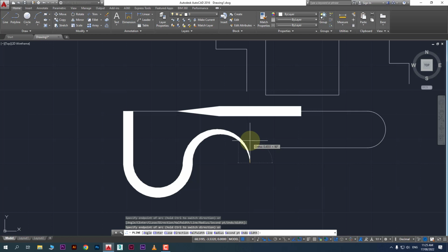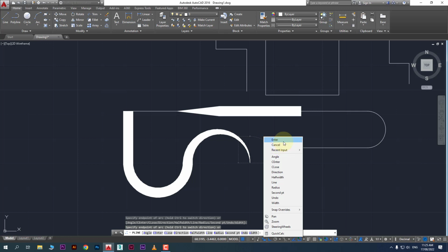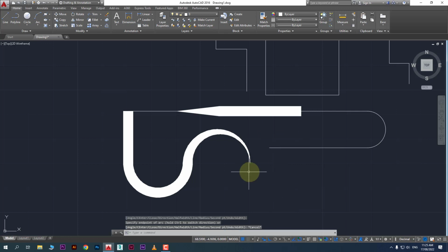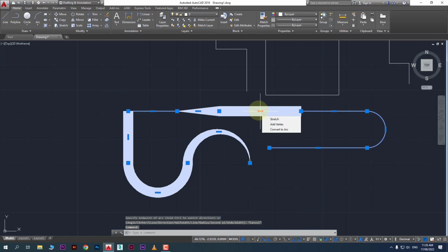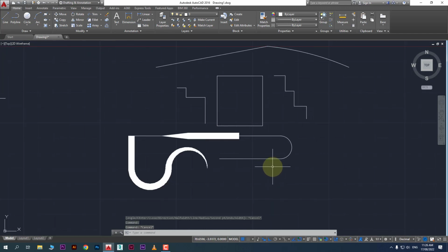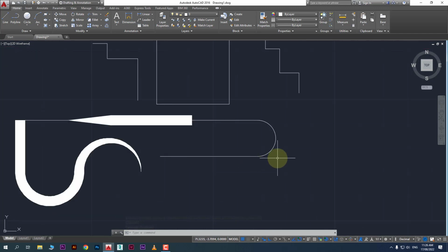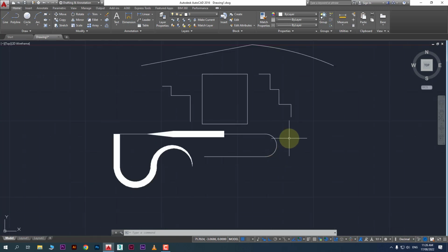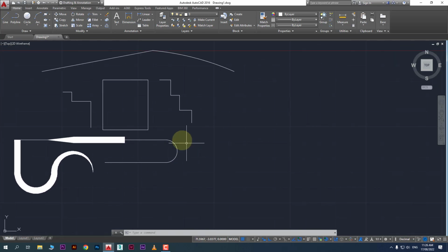Okay, so you can play with this polyline command like this. It's very useful. Now you can see it still has all options, convert to arc and this one and this one. Alright, so it's very important to use polyline in AutoCAD. Alright, so it's a line and the difference between polyline. Okay, next command we have which is called circle.